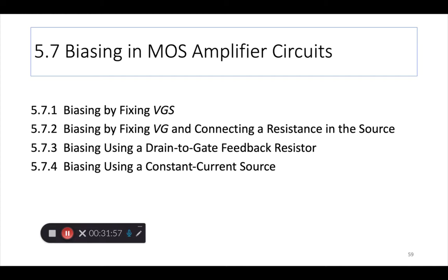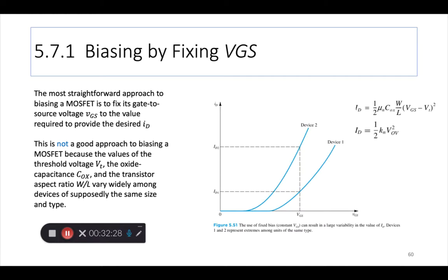We cannot go into the triode region or the cutoff region, but within the saturation region only a certain portion of the curve is good for linearity, right? And if you don't have a linear amplifier, you're going to find distortion between the input and the output. So your pure sine wave, or combination of sine waves, on the input is going to come out quite distorted if you're not in the linear portion. So picking the Q point is important, and some techniques to pick the right Q point is what we are going to discuss here.